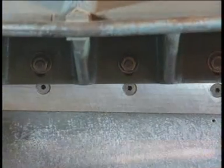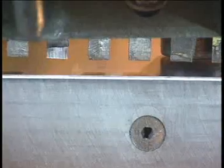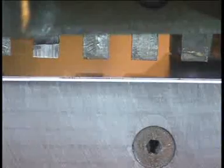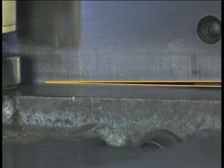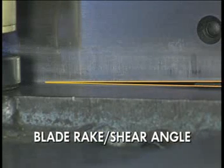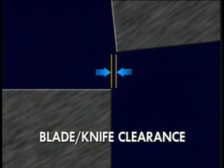In most shearing operations, the edges of two knives, a fixed lower blade and a vertically moving upper blade, meet progressively from one side of the workpiece to the other to shear the material like ordinary hand shears. The angle at which the upper and lower blades are aligned with each other is called the blade rake, or shear angle. The distance between the upper and lower blades is known as the blade or knife clearance.